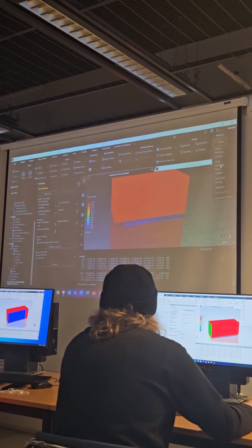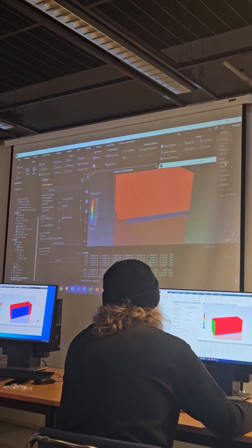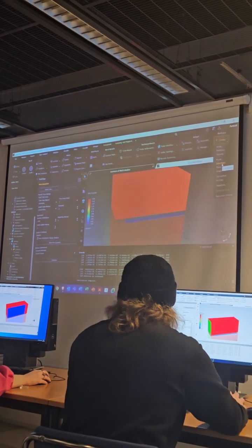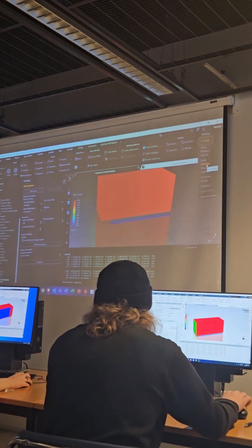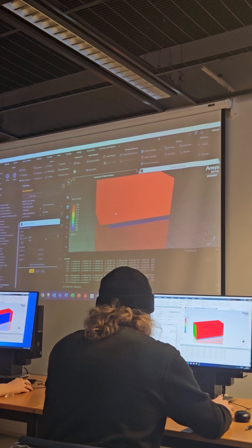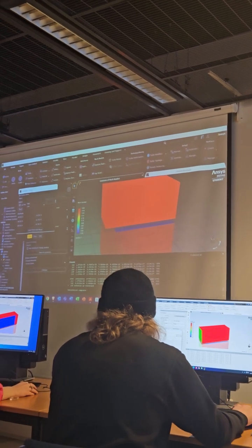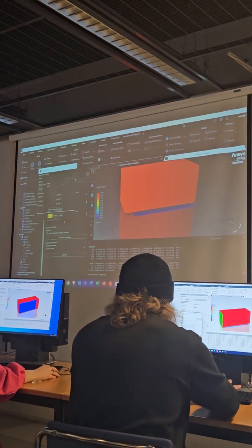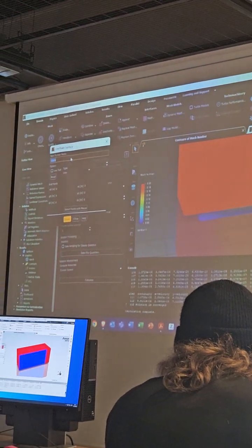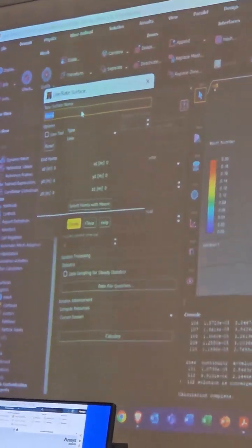And there I select the line, rake. Yeah, Domain, Surface, Create. And there is this option, and then Line. If you go from there, you will find this window where you can set the surface